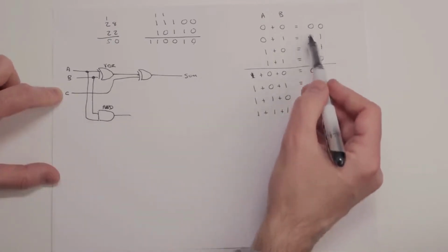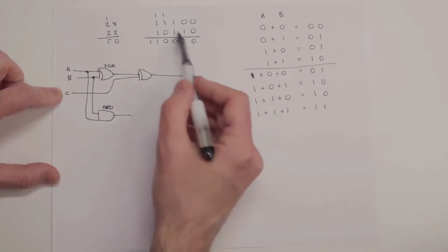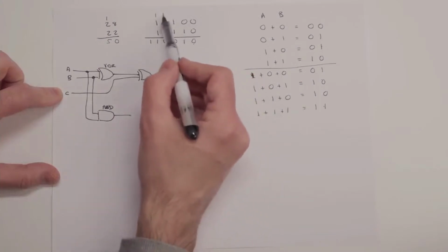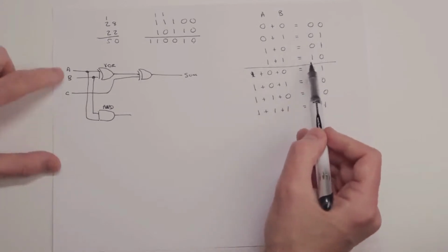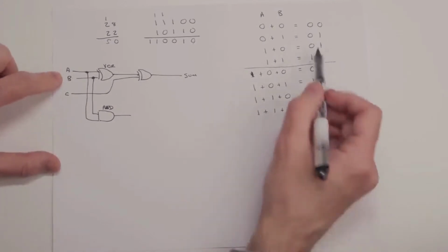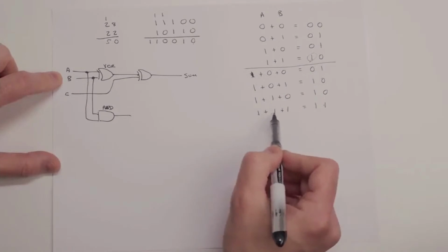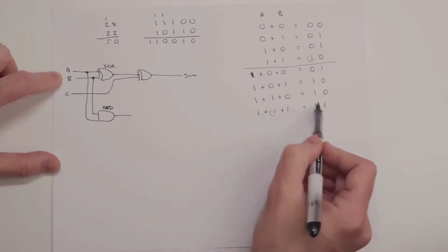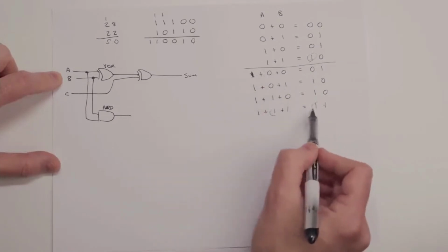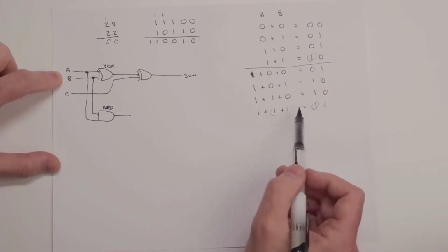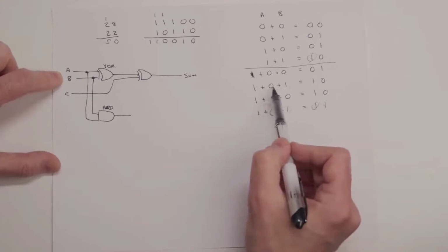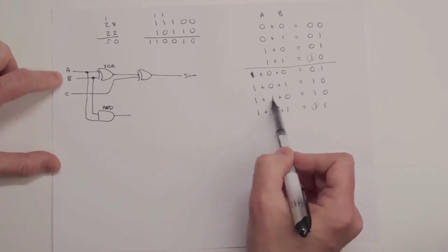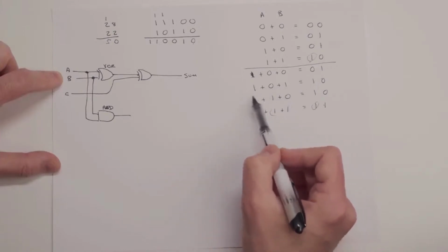Now for this first column, which is the carry bit that we might put into the next column, we've got these cases covered, right? Because if A and B is a 1, then we get our 1. And we even have this case covered here, because if A and B is a 1, then we have a 1 here as well. But what we don't have covered is these two cases here, where A or B is a 1 and we have this carry.